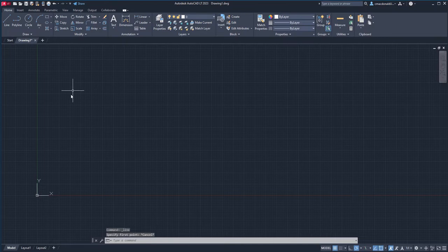So now if I go to make a line, I'm going to move up to the ribbon, left click, and start one anywhere. So I'll left click and release. And as you can see, it'll still let me essentially track to a horizontal line on the x-axis, left click. But now, as I rotate, it automatically wants to snap to one of those nice multiples of 30 degrees, whether it's 30, 60, 90, 120, just like that.